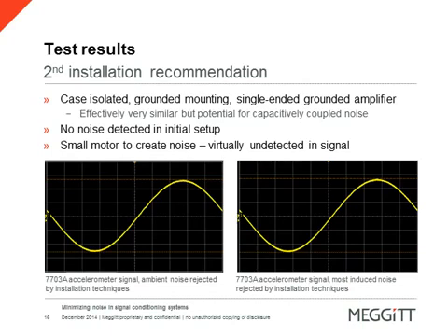And explaining that a little bit, when you have a grounded accelerometer, any electrostatic buildup is bled into the low side, into the ground side of the accelerometer system. When you have an isolated mount, that cuts the path for a signal back through ground, so you don't have that electrostatic buildup into the ground system, or a difference of potential. With the isolated case, you do have a potential with electrostatic buildup in there, because inside the accelerometer, your low side is still connected. It's not isolated from ground. So there is a potential between the amplifier ground and the signal of the accelerometer.